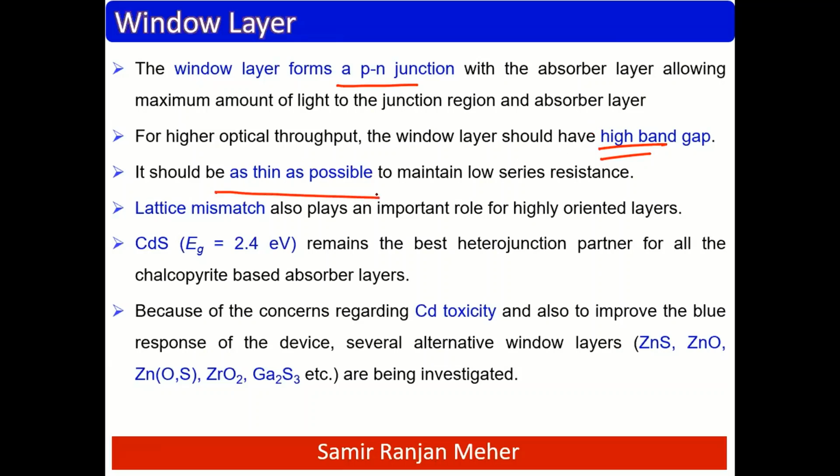And together with that, it should be as thin as possible, because if it is very thick, then automatically the absorption of the photons will take place in the window layer, and also the series resistance of the device will increase. And it should have a good lattice match with that of the other layers.